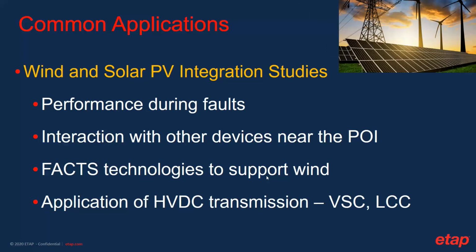Now, over the last 5 or 6 years, electromagnetic transient simulations are becoming very important to study the integration of power electronic based devices. Now, with wind and solar and also HVDC becoming more and more common in power systems, the importance of electromagnetic transient simulations have increased. So it is common now to perform EMT type studies to identify the fault ride-through performance of wind farms, HVDC, and solar farms.